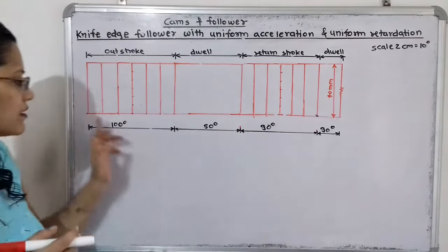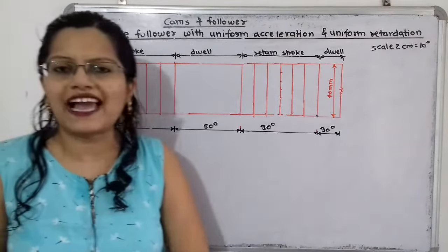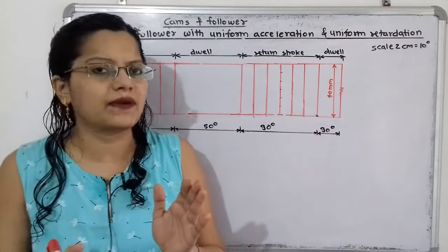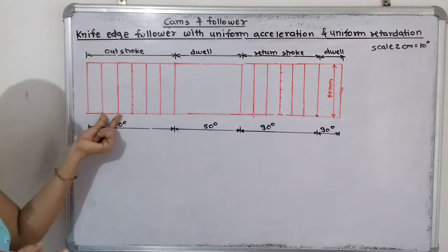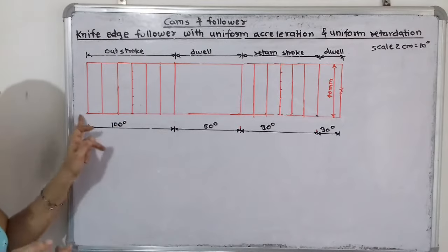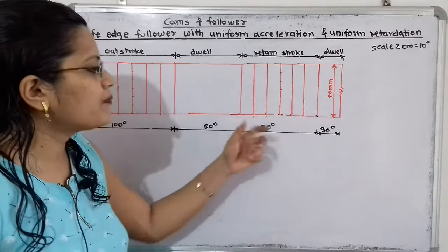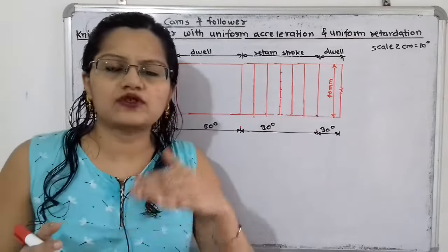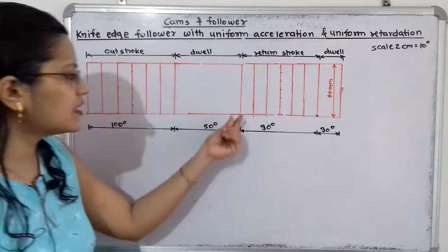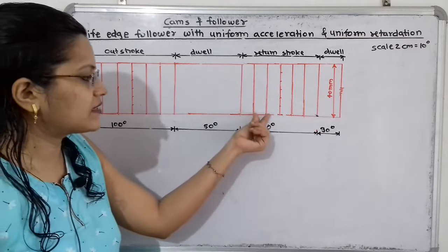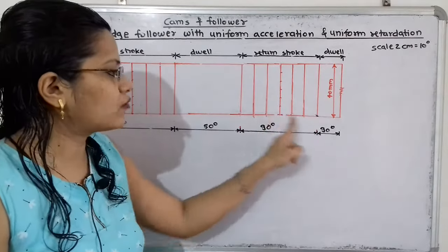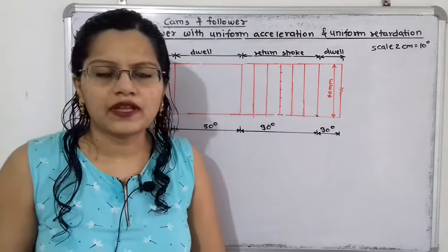On calculator we can make 20 divided by 6 and that distance we will select here, and these are the 6 equal parts. Same here for the return stroke also, this scale is 18 cm. So 18 divided by 6, that is 3 cm each, and we have to mark here the points.